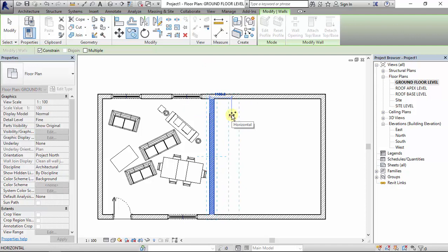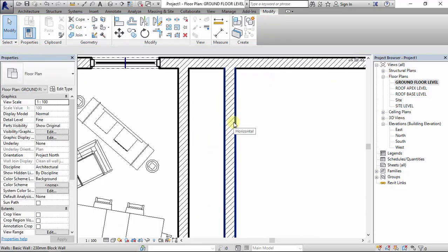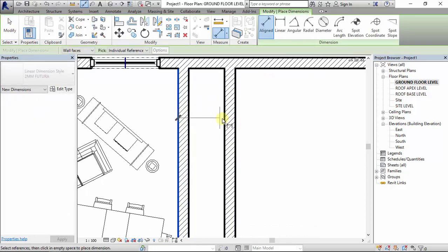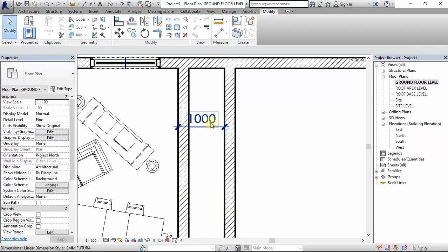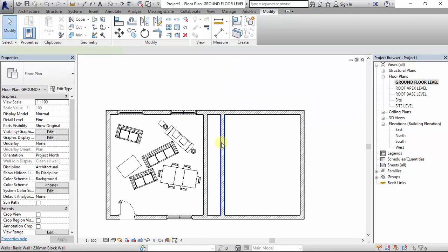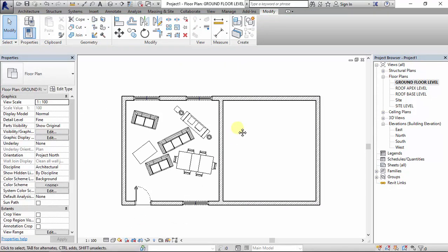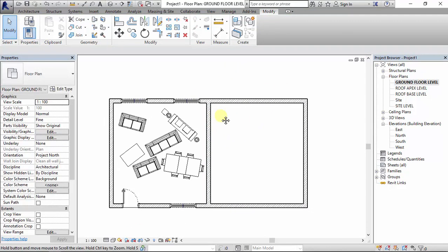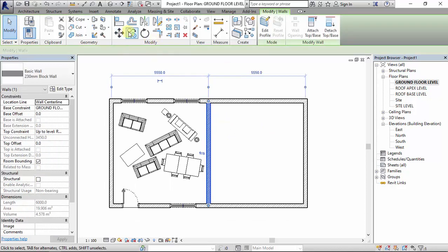Copy, for example, press equal to 2 meters /2, so that's like 2000 millimeters divided by 2. Then hit enter. Then we can confirm the dimension, and we see that we just moved the wall by 1 meter.